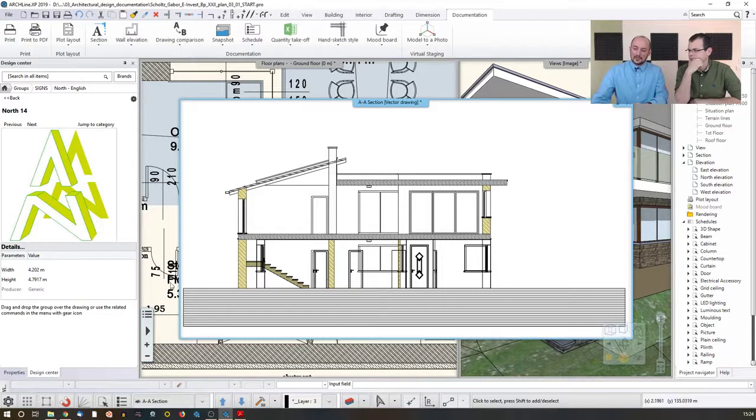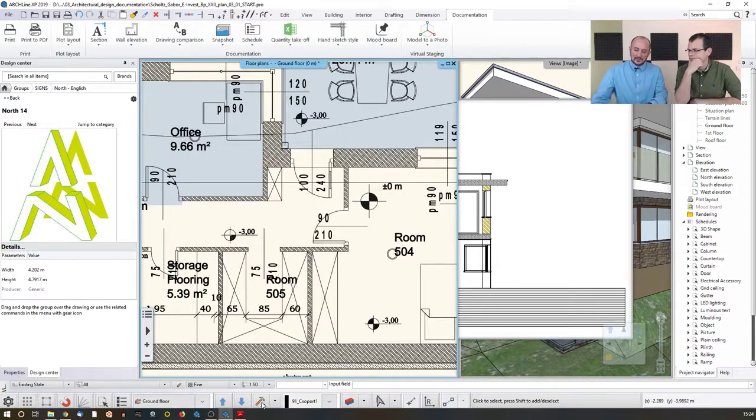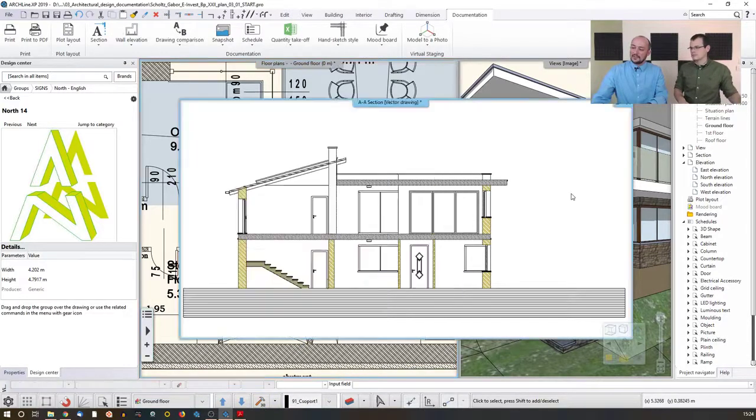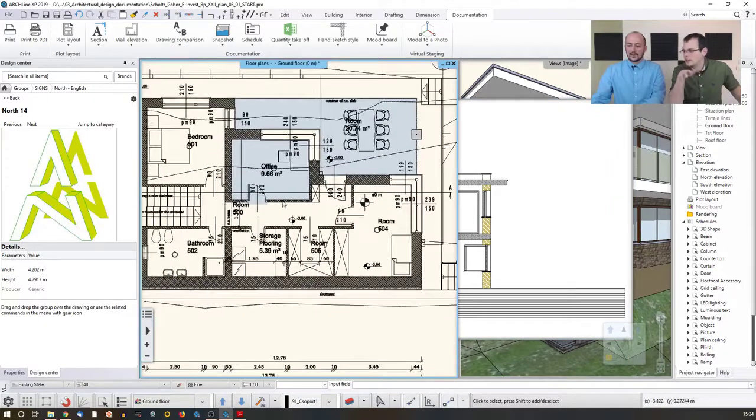But whenever you click on the 3D rebuild, the 3D update option, the software will not only rebuild the 3D, but it will also update the connecting drawing. So now the wall is actually moved and the section is properly represented. If we go back to the section line, and maybe we want to make a cut into that, maybe we want to have that part go below the room.